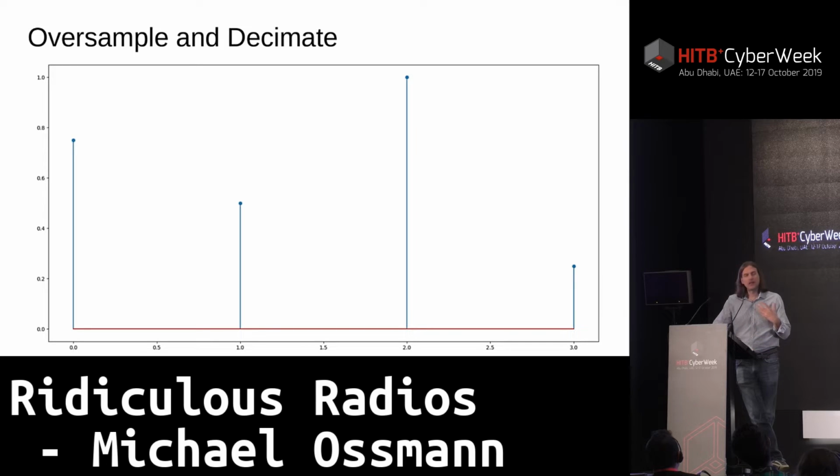In practice, what people do is not this very crude way of just averaging 2 samples at a time. They do something slightly more sophisticated where they take a bunch of information from many more than 2 samples at a time and use a low-pass filtering technique.